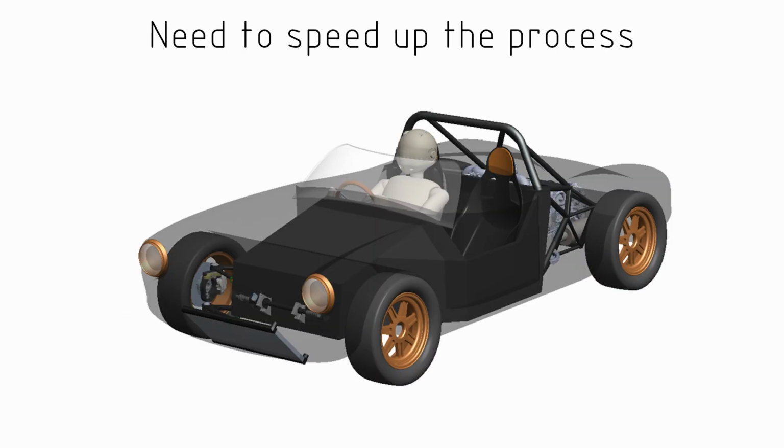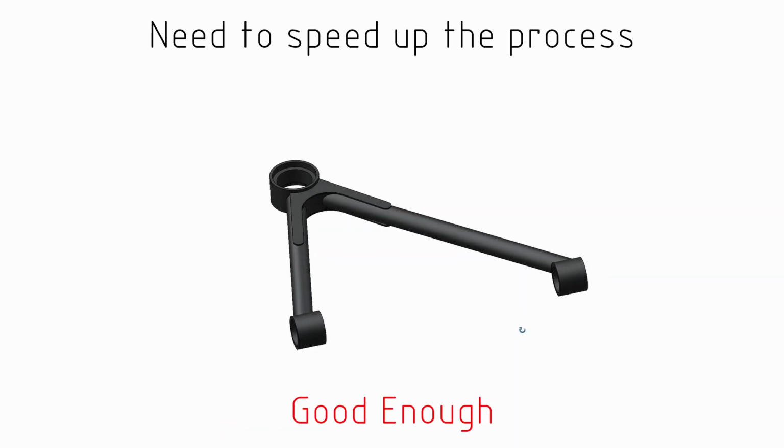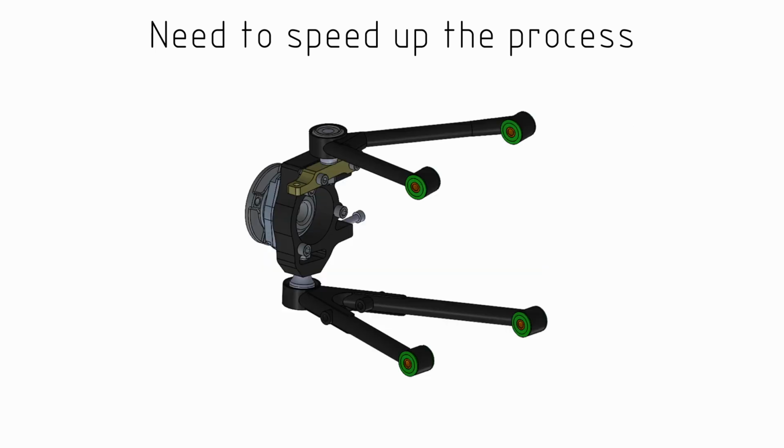Now that's going to mean that I'm not going to model every last detail of the car. There are some things where I'm just going to go, yep, as soon as it's at that point, it's okay, I can go ahead and manufacture it. That might mean, for example, not putting every last feature of a purchase part and modeling those purchase parts relatively roughly to make sure that I've only got what I need and no more. In some places, it might be leaving out fasteners or small details.